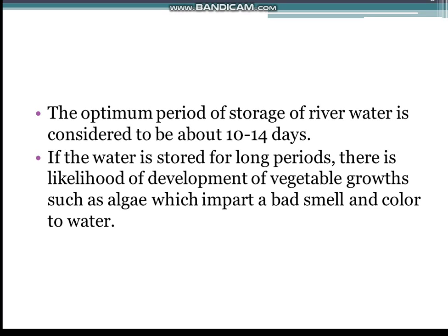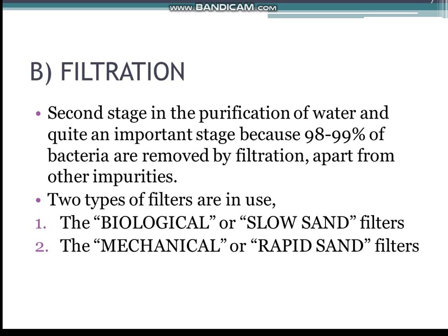The optimum period of storage of river water is considered to be about 10 to 14 days. If the water is stored for long periods, there is likelihood of development of vegetable growth such as algae, which impart a bad smell and color to water.